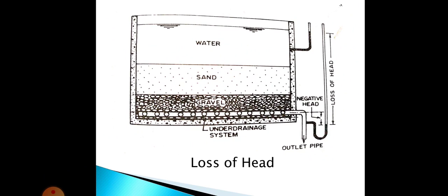Then the filter will become airbound, and the head loss also will rise sharply, and the filter output capacity will drop. So then the rate of filtration also will reduce considerably.